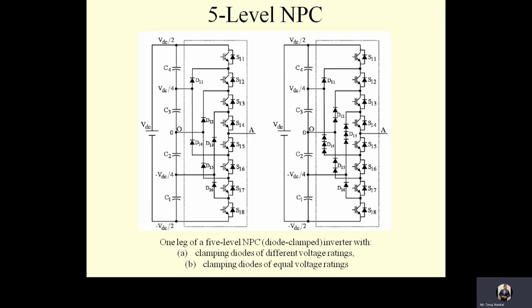In the multi-level inverter based on neutral point clamp strategy, voltage across the series connected capacitor is assumed to be constant to achieve equal sharing of DC link voltage among the switches.